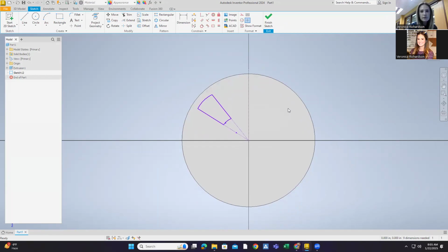Okay, so at this point in my drawing, I've drawn both of my straight lines, I have both my arcs, I have construction lines in, and I've also started to use my first constraint, which is called the collinear constraint. If you are not sure if you have done that already, a good way to check is to click on both of your straight lines, and you can make sure that you have that symbol next to each one. If you do, that means you've already used the collinear constraint and you are good to go.